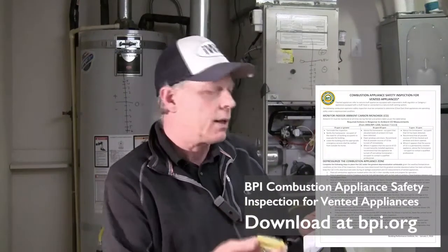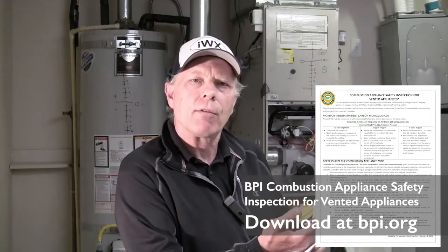Even if I have 0, I need to let the proctor know I know where to refer to the ambient CO levels, and I have this document here that I got off the BPI website that will be provided to people who come here to take the test also. This is where we refer to the actions required at different levels of ambient CO. We're at 0, so there is no action, but you still need to make a statement to the proctor about that. Later on, you may be working with an oven, or you might get some spillage off the water heater. And if CO shows up, you need to be able to show them you can refer to the sheet and know what needs to be done in those cases.